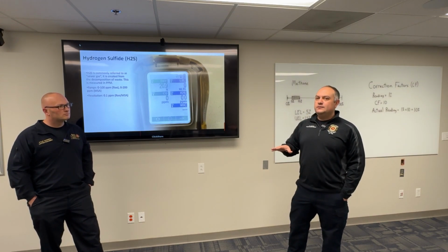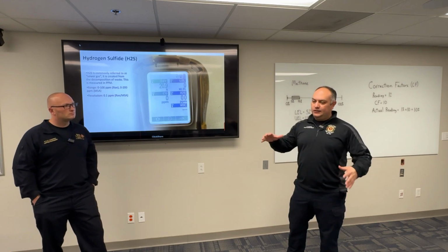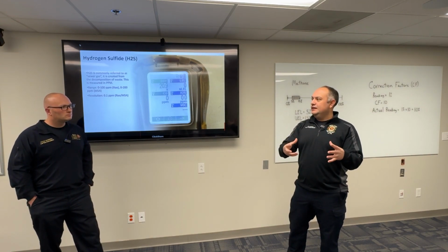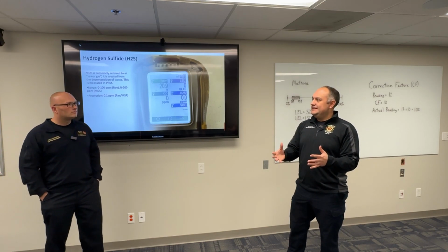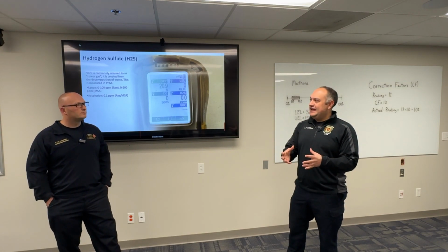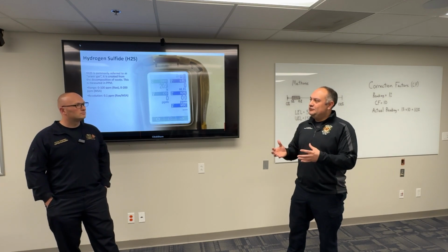The part where it becomes dangerous is when that sewer gas accumulates in a confined space. If we think about a sewer, by definition, it is a confined space. It's not something that's continuously designed for human occupancy. It's got limited egress and access, and it's some place that's enclosed that can really trap something.